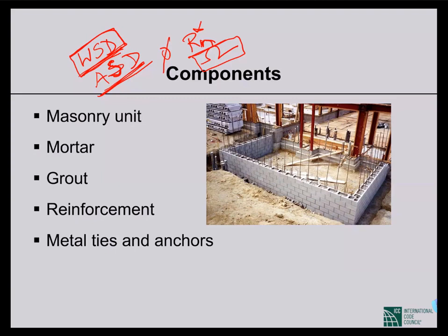So implicitly, if we have to follow the tables, the maximum masonry building can have a height of 5 stories. There is no table which mentions masonry construction for more than 5-story buildings.